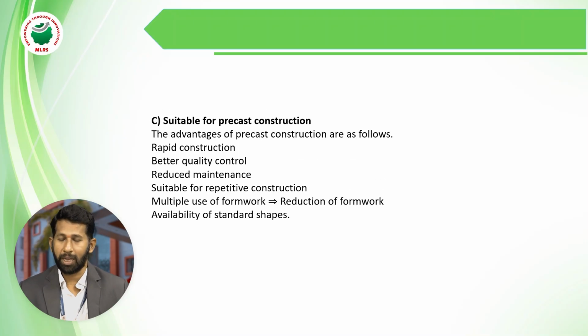Suitable for precast construction. The advantages of precast construction are as follows: rapid construction, better quality control and reduced maintenance, suitable for repetitive construction, multiple use of formwork, reduction of formwork, and availability of standard shapes.